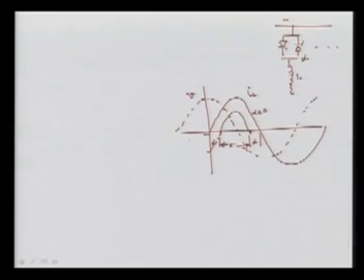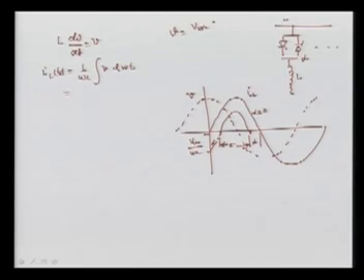So this is the case, and the value which is appearing here is your Vm over omega L. Now I can write this expression here. As we know, L di by dt is nothing but your V, and this inductive current in time, I can say is 1 over omega L times the integration of V d omega t. Now I have just changed the dt here. Let's suppose V is Vm cos omega t.